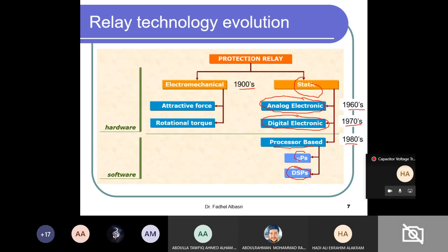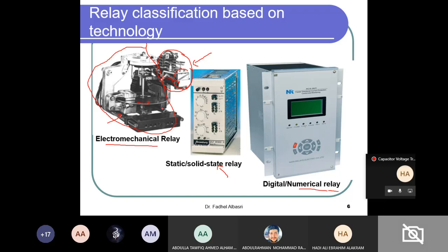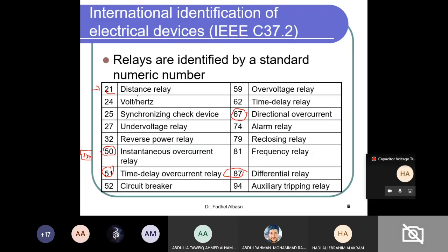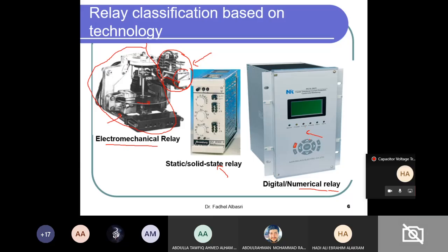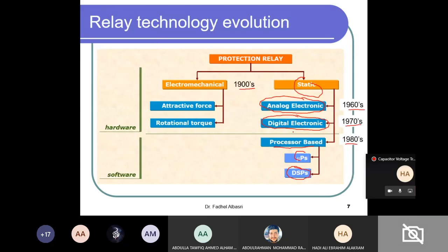So now these protection functions that I mentioned are not hardware; what's inside this box is also software to implement the overcurrent or the distance. How do you measure distance Z? I have to measure the currents numerically, by using digital signal processing instead of hardware measurements.